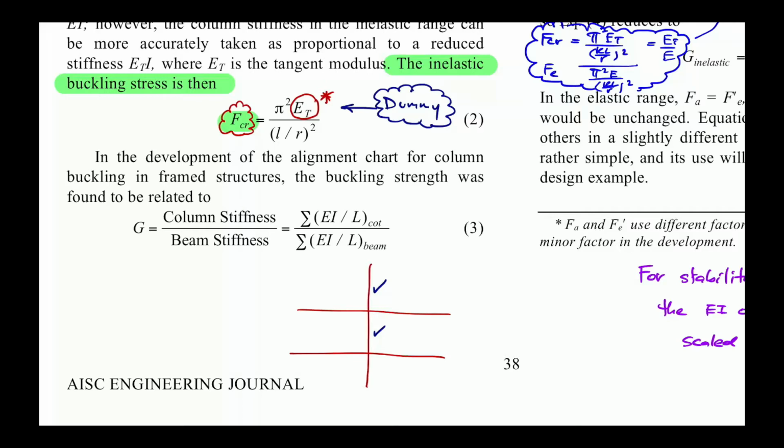In reality, you might have the top column being steel, the other column being concrete, whatever. So the formula gives you the flexibility, it gives you the EI over L. And if you think about EI over L, you remember it ties up to the rotational stiffness.